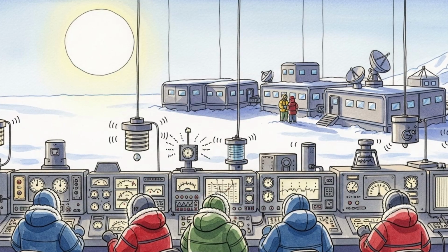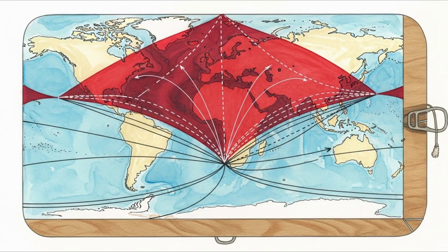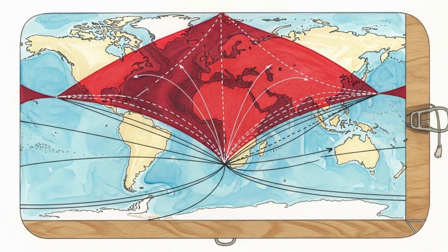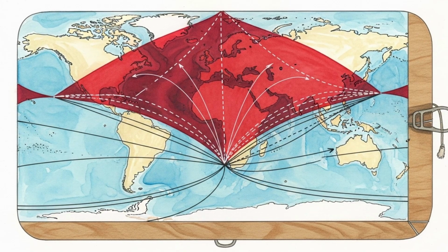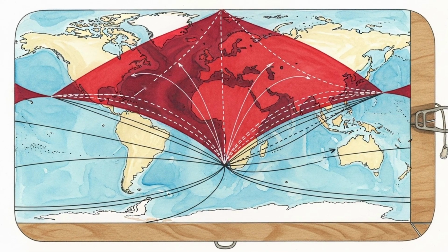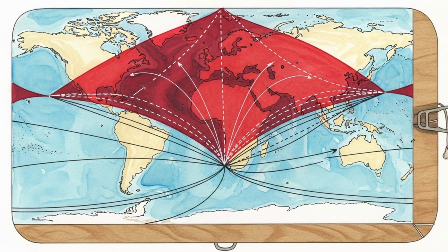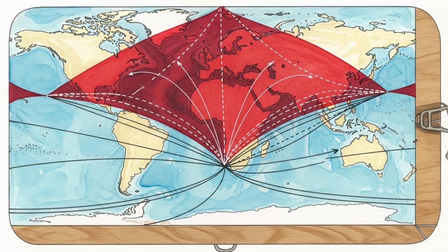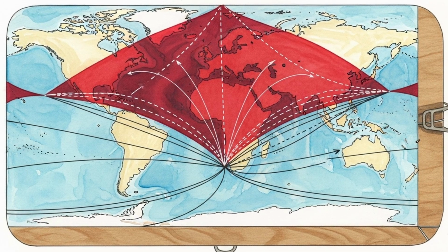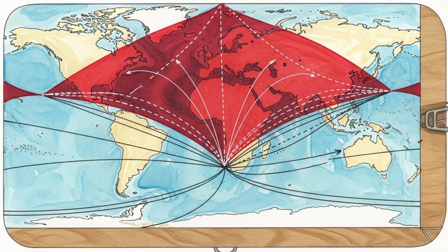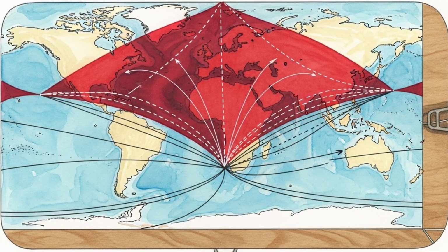Coastal regions and sedimentary basins tend to see larger induced electric fields than shield areas with low conductivity. Planning studies combine these maps with power flow models to identify substations where monitoring and mitigation bring the most benefit.